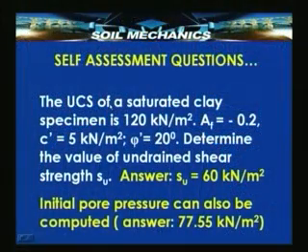Try to also solve a simple problem. For example, here the unconfined compressive strength of a saturated clay is given, and when it is subjected to a triaxial shear test, the pore pressure coefficient AF is found to be minus 0.2, C dash and phi dash determined from the test are 5 and 20. Now, try to find out the undrained shear strength.